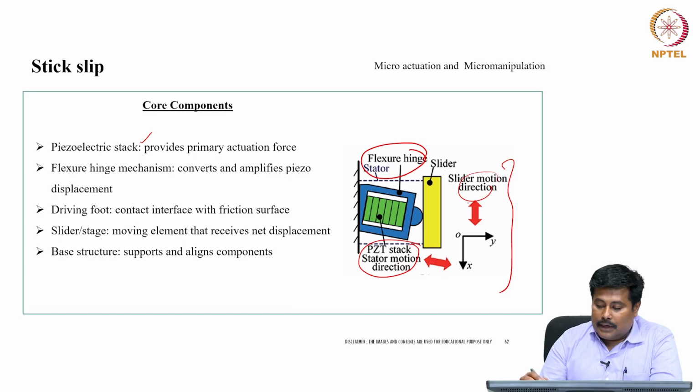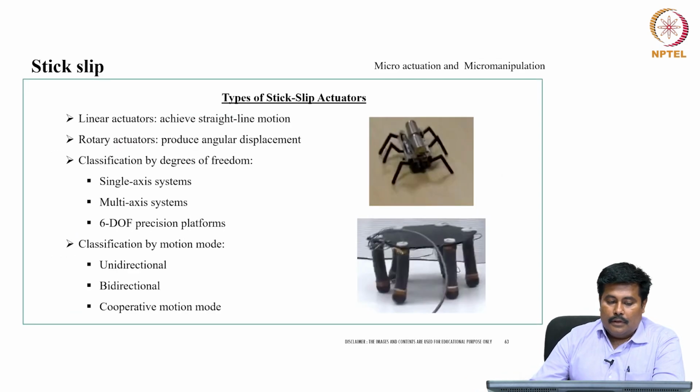So these piezoelectric stacks provide the primary actuation force, a flexure hinge mechanism which converts and amplifies the piezo displacement, a driving foot which is the contact interface with the friction surface, and a slider stage, which is the moving element that receives the net displacement, and there is a base structure which supports and aligns the components.